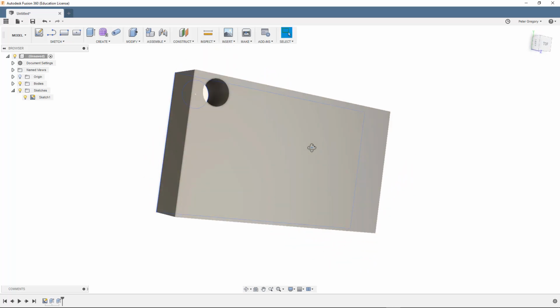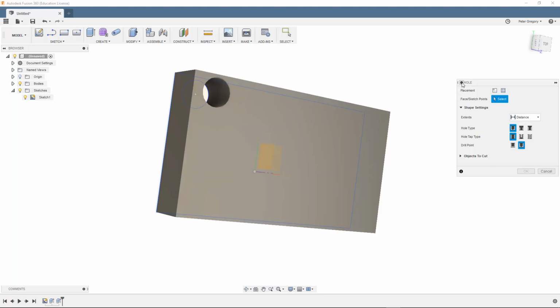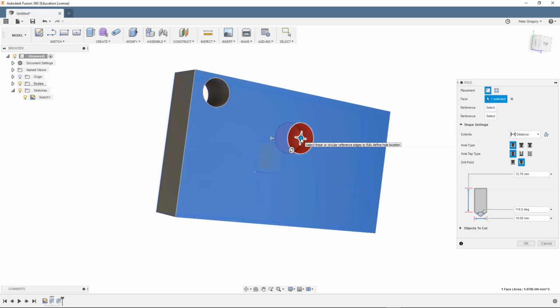Now, the thing that I found out in the book that I had not been using, I don't remember using this before, is actually just using a hole. Okay, so we can enter a hole. There are very few commands in Fusion 360 that have keyboard shortcuts, but it's important when there's a hole. Instead of doing that extrude business, you can just punch through and make a hole. It anticipates something here that I'm wondering about. I do 3D printing, I don't do CNC with this, and they set up some drill types, some drill parameters here if you want to set this up for how it's actually going to be drilled.